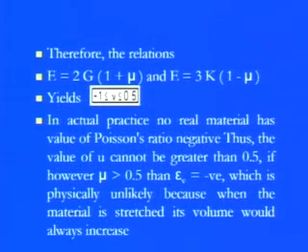So now, based on the previous relations which we set up, the Young's modulus of elasticity equals 2 times G into (1 plus mu), where mu is the Poisson ratio, and E equals 3 times K into (1 minus mu). If I keep those things, then the key feature in both formulas is the mu value, that is the Poisson ratio, which always lies from -1, less than or equal to mu, which is less than or equal to 0.5.